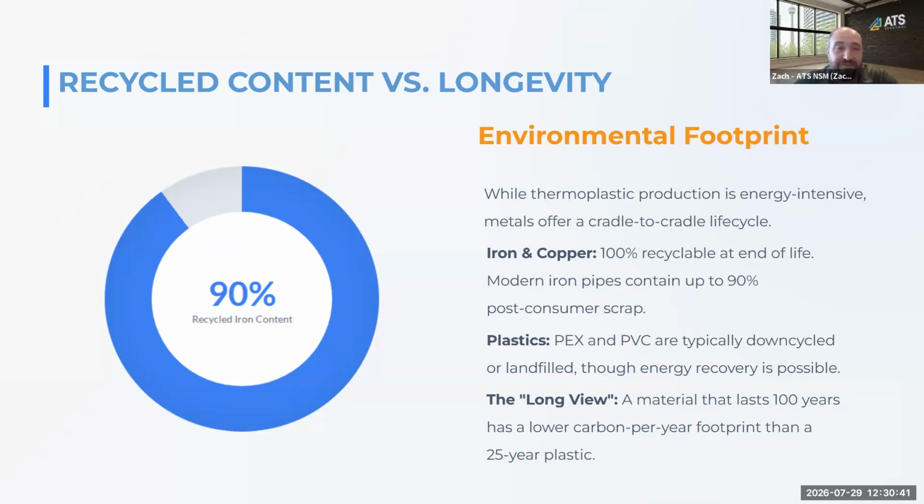The battle that we see every single time we help out with a LEED project is that every point matters. We battle over minutiae in flow rates to make sure we are providing faucets, showers and flush valves that help meet it. This is another LEED point that can be pursued. The distance from a location to the project is one LEED point, and there are recycled content LEED points. So keep that in mind as you are going through.